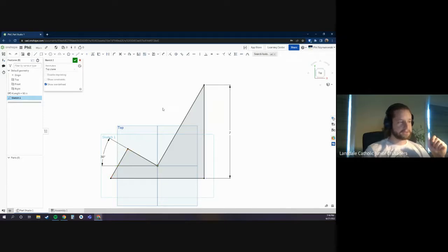But if I do that same selection from the top right and down, like this, drawing to the left, like creating the rectangle to the left, I will be able to select all 3 lines, anything that's just touching the box, even if I don't have it fully selected. So like if I move over to here, I'm going to select this angled line as well.